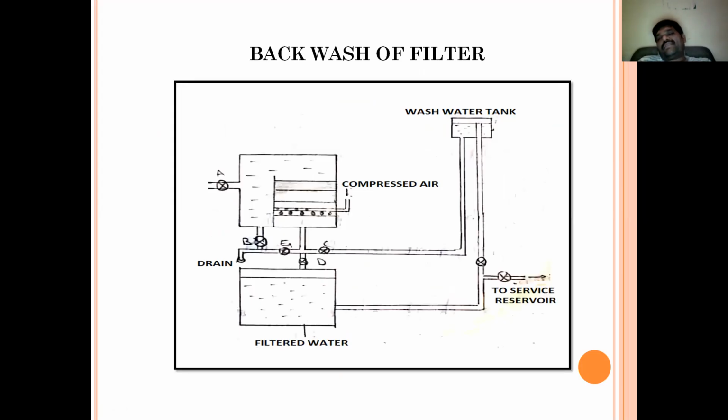See here, in the previous case, we have seen that 2 to 3 centimeters of sand on the top of the sand bed will be removed, washed and dried before we continue the process of the filter. Whereas here, no such removal of sand from the top of the sand bed, drying or washing exists. The whole process and mechanism does not exist in rapid sand filters.